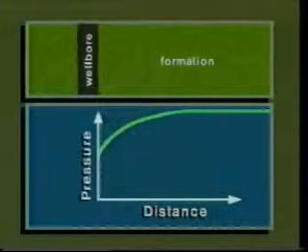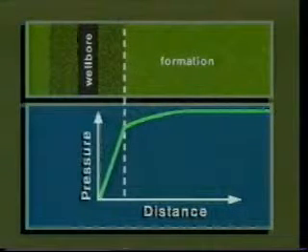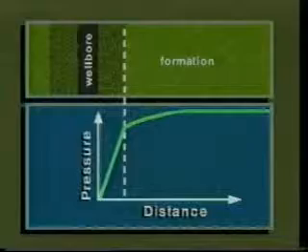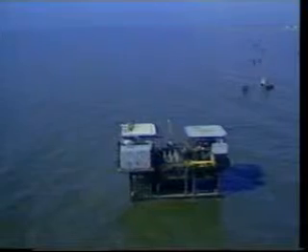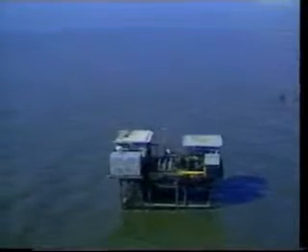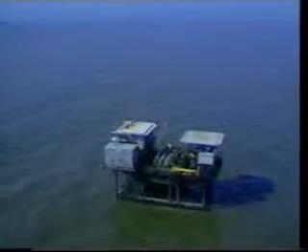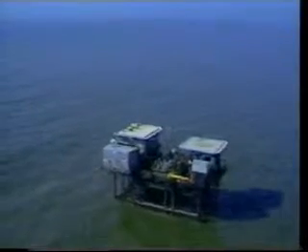Poor completion efficiency will result in near wellbore damage and increased drawdowns, and that can lead to possible sand movement. The main aspect of completion efficiency is to employ perforating techniques as described in PE 303, perforating. In certain areas, rate control and the natural arching of formation sand can be effective sand control methods. However, the rate necessary to control sand production is often very low and thus adversely affects the economics of the well.